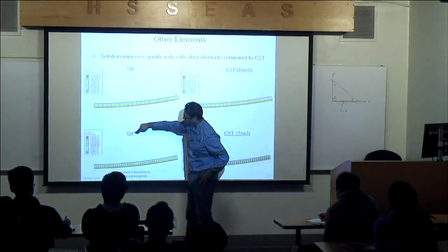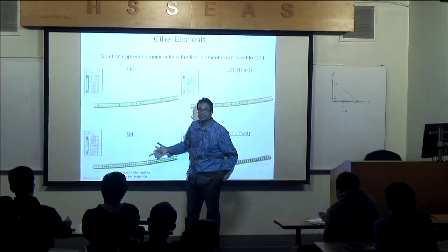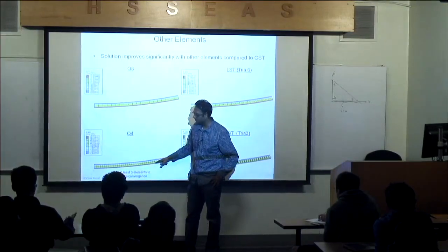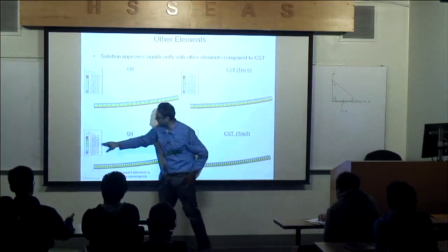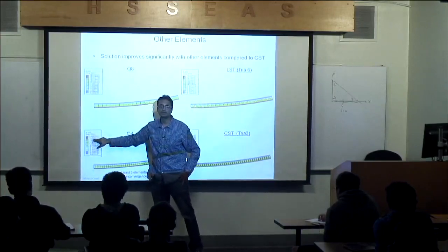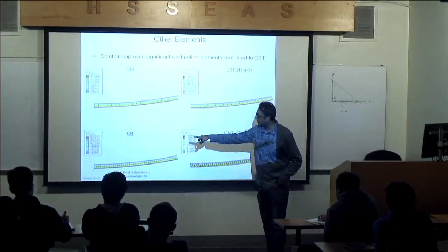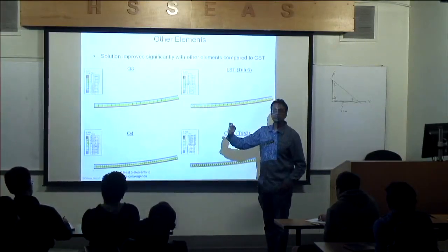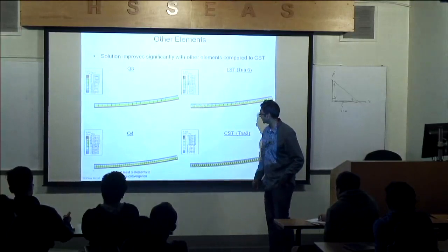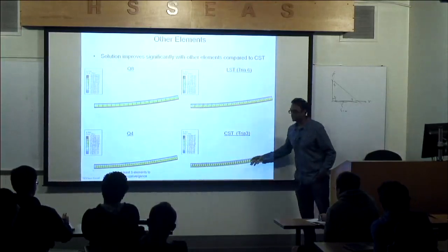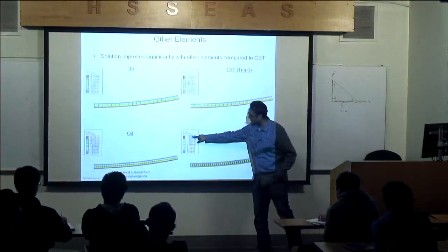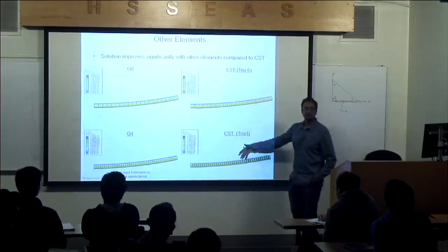These two are very close to the exact solution. Now for Q4, let's add an extra row of elements, just for fun. Even this one is still stiff, 5.8E7. Still not as good. If you want to get good behavior with Q4, use at least three elements per thickness to model bending very well. This is a constant triangular element. Don't want to even cover it. That's about half the stress, so even talking about it is a waste of time.